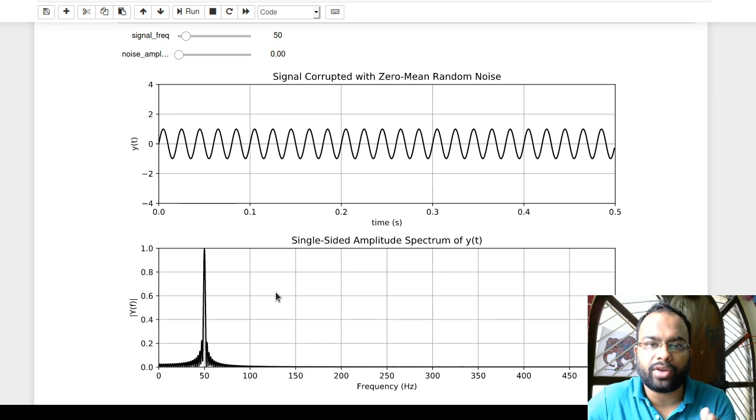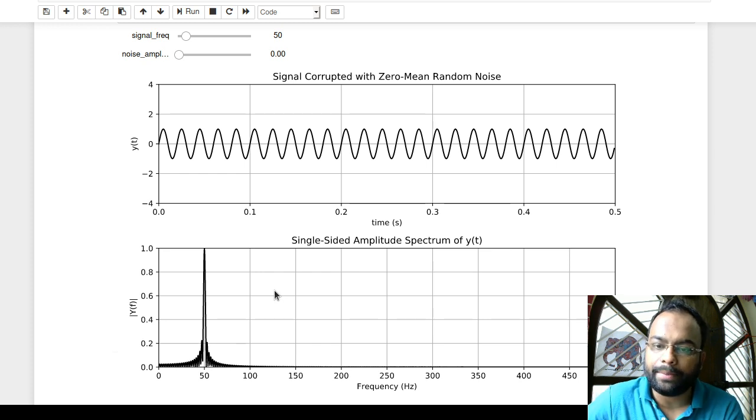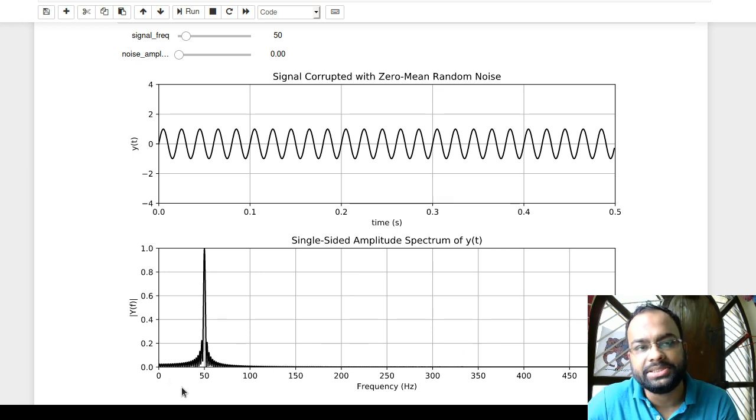So again, Fourier transform, the expression that we get, X(omega), is a complex expression, and if we take the magnitude, what we get is called the amplitude spectrum. Okay, we shall discuss those terms, don't worry. So we get the amplitude spectrum. So for example, look at what we have here. We have a signal which is a pure sinusoid, and we have taken the amplitude spectrum of that, and again it's a digital version of the Fourier transform. So yeah, let's keep that in mind.